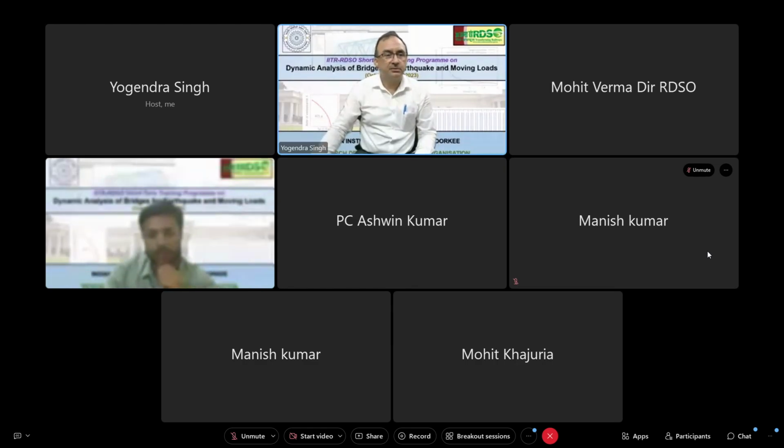Mr. Lalit is asking, while doing response spectrum analysis for closely spaced mode shapes, shall we do CQC for modal combination or directional combination? What is this directional combination actually used for? Okay, so earthquake has 3 components. Earthquake rather has all the 6 components. So during earthquake, the motion at a point has all the 3 translations and all the 3 rotations. All 6 types of motions are there. Instruments which are available so far cannot measure the angular acceleration. So that's why this angular acceleration you will not find in most of the textbooks.